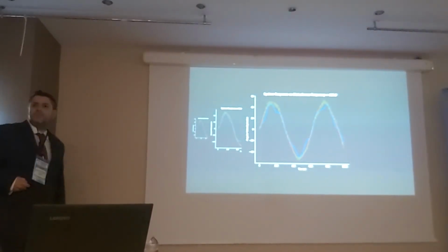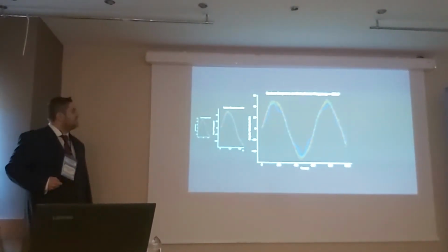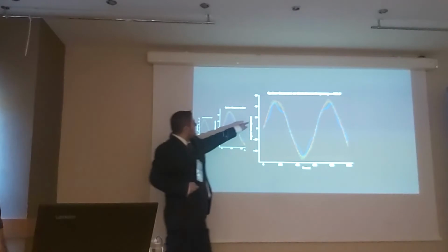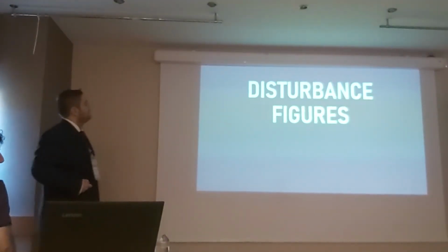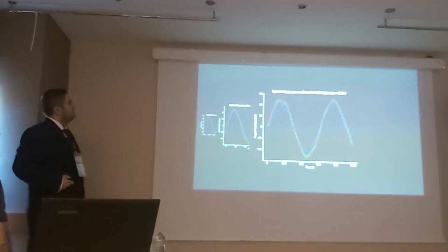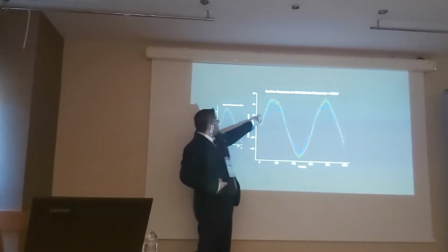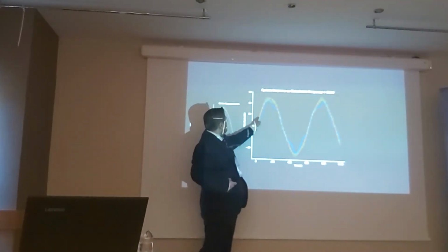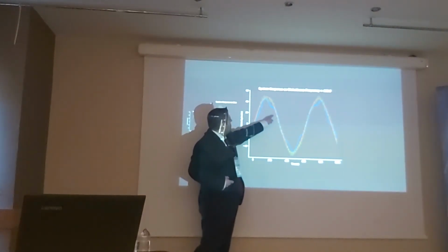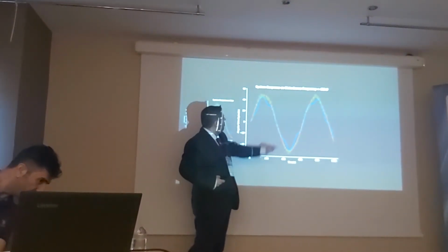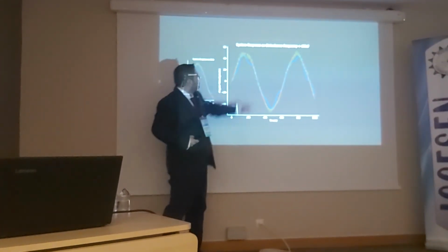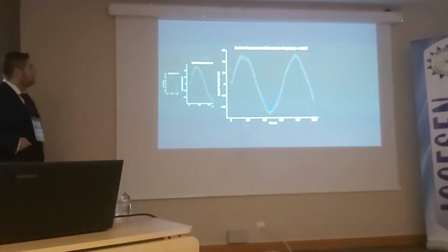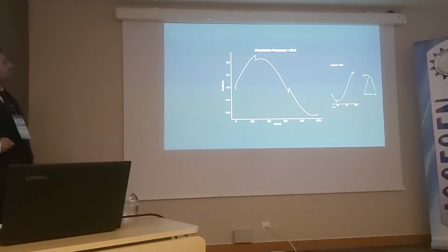As the frequency of the disturbance increases, you can see that there are more deviations from the reference trajectory. The red one is the reference trajectory, the green one is the particle swarm optimization tuned controller trajectory, and the blue one is the Ziegler-Nichols tuned controller trajectory.